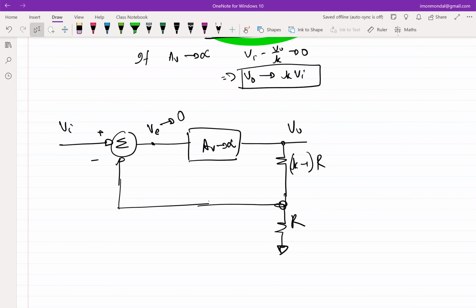So there is one important aspect. Once you have set up the negative feedback loop, or maybe somebody has given you a negative feedback loop, the first thing that you have to ensure is the direction of the loop. Which means, are you correcting the error in the right direction, or are you going in the opposite direction? I could have as well said that instead of AV, I'll have minus AV, right? In that case, it obviously wouldn't have been fine. I need to turn my handle in the right direction. I'm seeing the error, but if I turn it in the other direction, there's no point. So the direction of the loop is important.